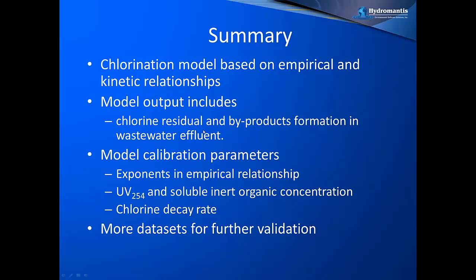Now, in summary, the chlorination model that we developed is based mostly on empirical relationships that are published in literature, as well as some kinetic relationships, especially with respect to the chlorine decay. When you start using the model, you will be able to see the chlorine residuals in the combined form or the free form, and it can also show the byproduct formation potential in the wastewater.